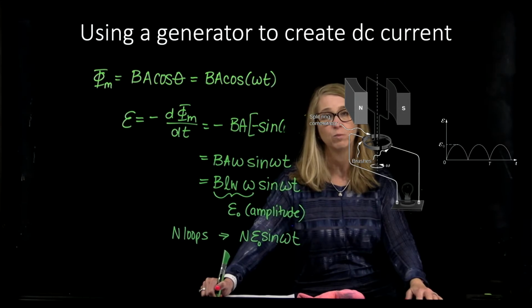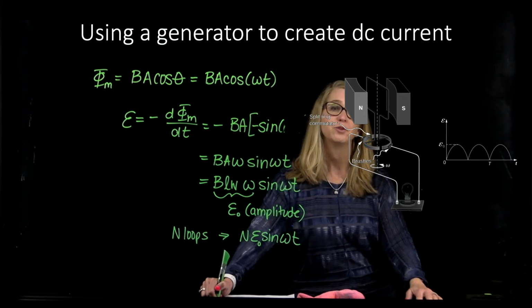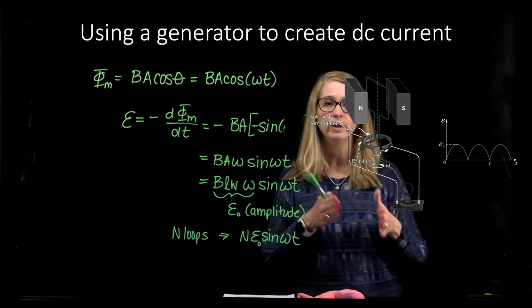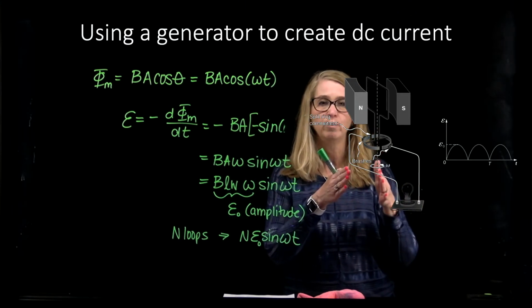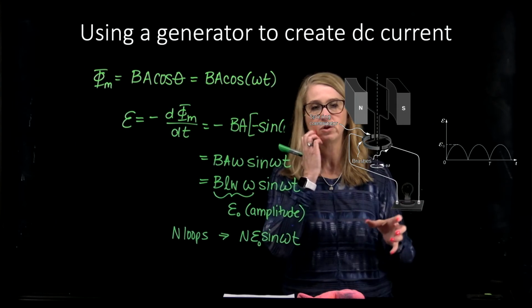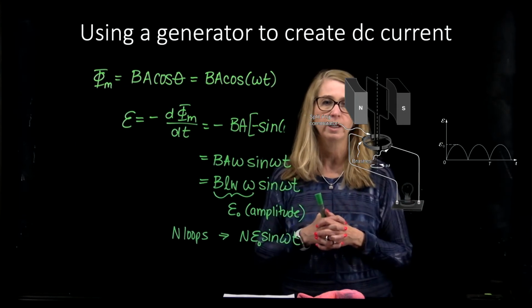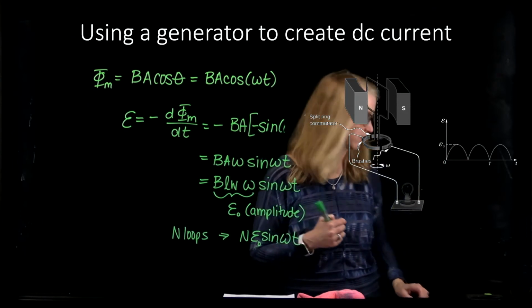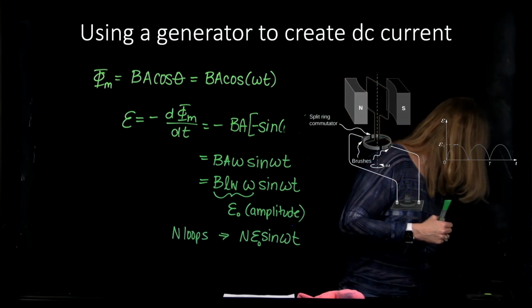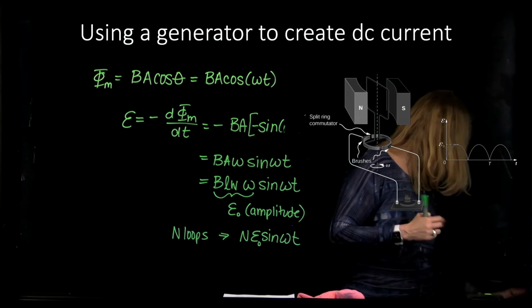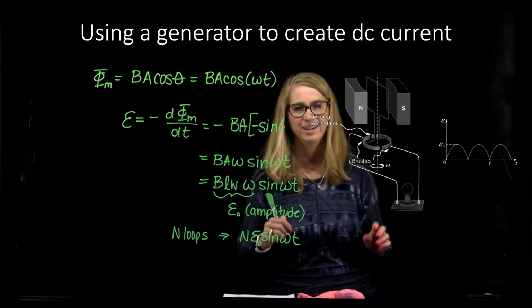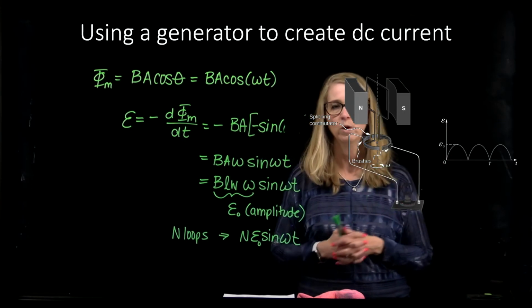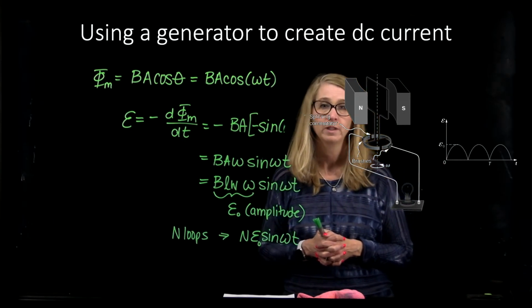And then we can have more of what we would think of as a direct current. Literally having just that split ring that connects to the rest of the circuit can allow us to go from the totally oscillating picture to something that's more of a direct current.